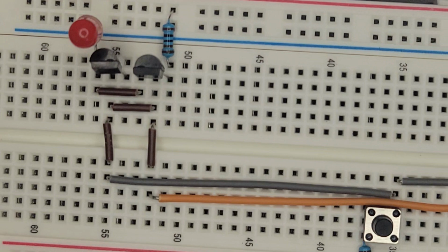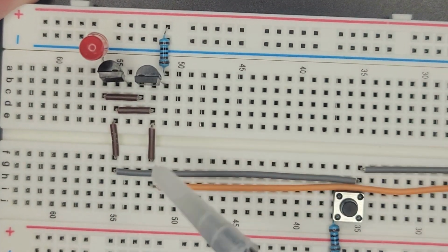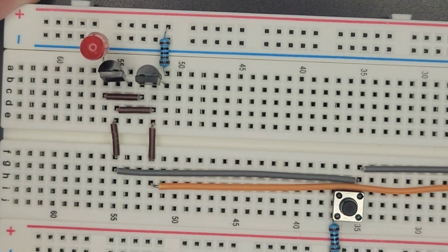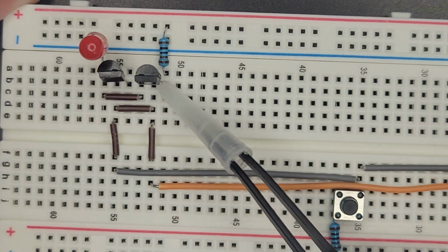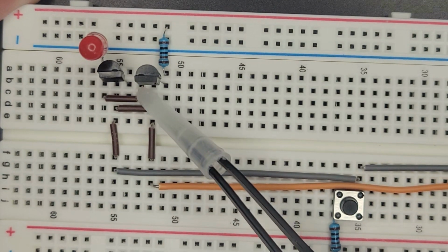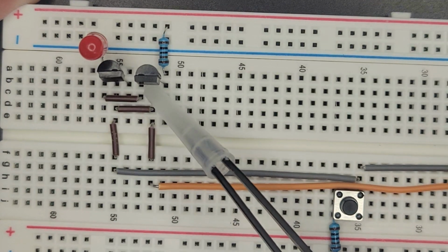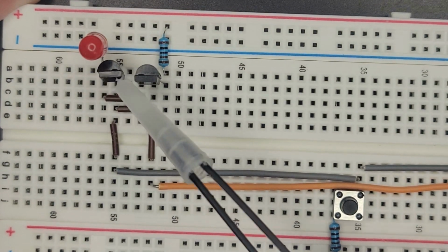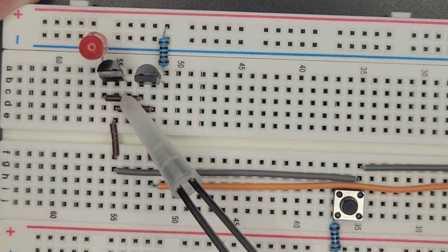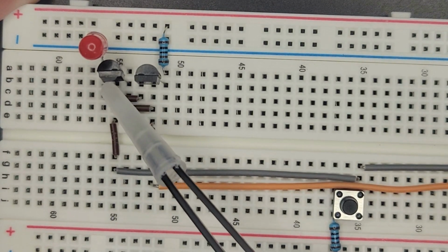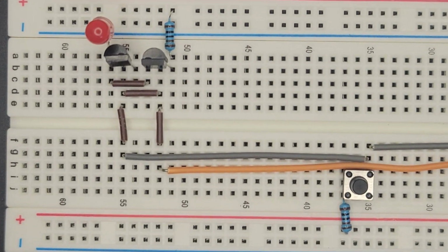I think I zoomed in a little too much. So we have our resistor going to transistor A. When A is pressed, right, orange wire over into the base, he's energized, collector can emit. And whenever the base is activated here, it's also activated here. And he emits his power into this guy, who then, since the base is activated from either one of the buttons, since the bases are connected, he'll emit out to the LED. So I think we can plug this in and try it.